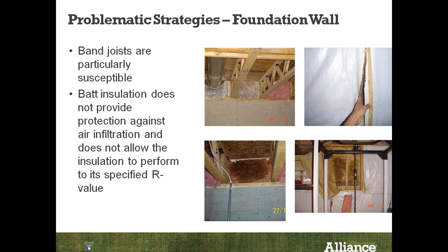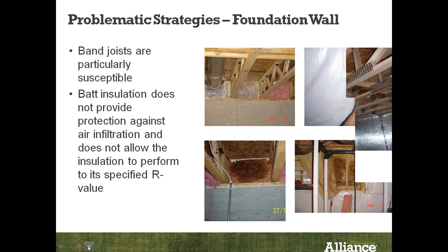we call them garden walls, where there's a walkout basement and there's a framing portion of it, where typically these framed walls are insulated with fiberglass blankets. And these are areas where the blanket has a vapor retarder on it, but they're not sealed very well. And these little gaps cause vapor to pass through leakage points and condense on cold sheathing surfaces.